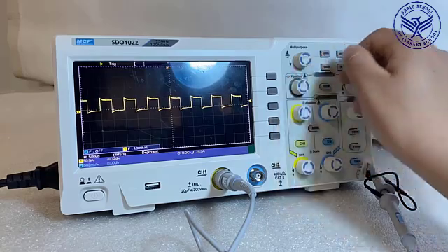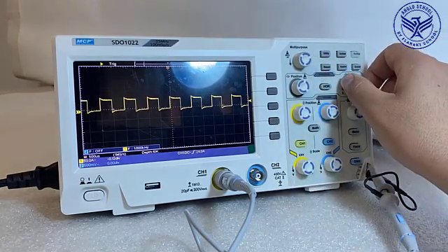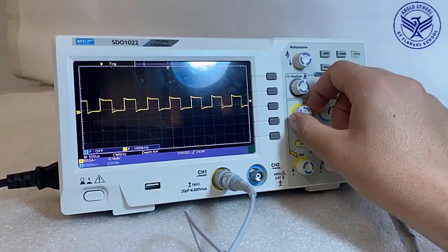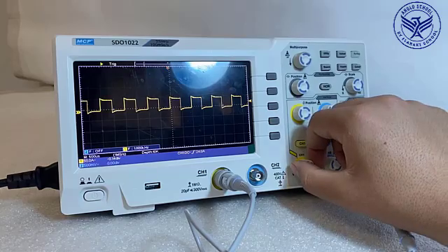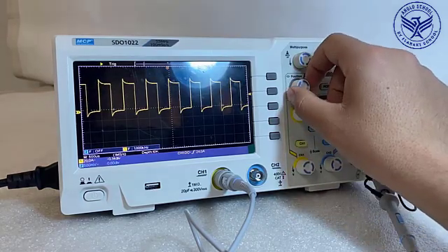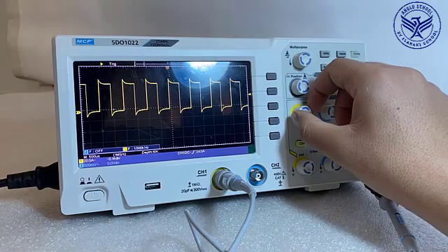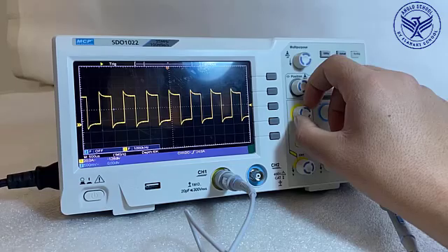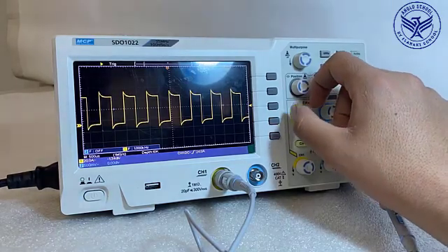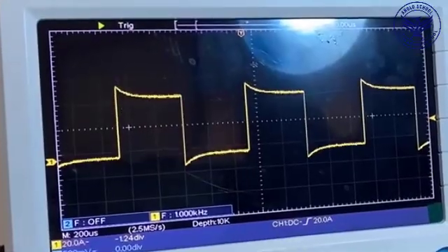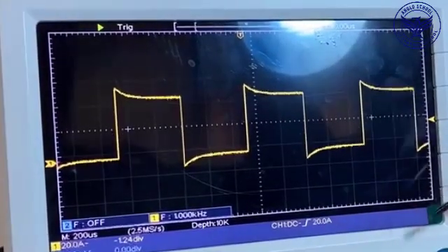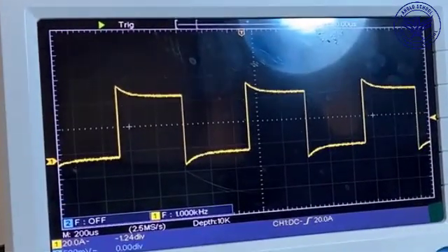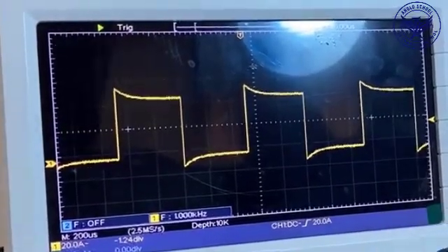If the waveform seems to be moving or jittering, this is because the scope has no idea when on the waveform to start measuring, but we can fix that by adjusting the trigger level. Use the knob in the trigger section to raise the level to somewhere between the min and max of the waveform. This tells the scope to begin measuring as soon as it sees a rising edge, perform one sweep on the screen to draw the waveform, and then repeat the process. Note that digital scopes like this can store and display information before the trigger. Because this is a periodic waveform, the image appears static on the screen.